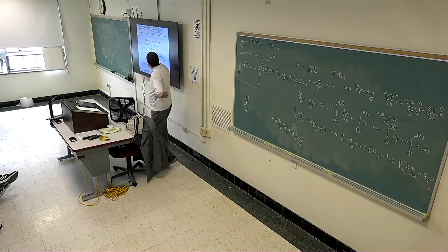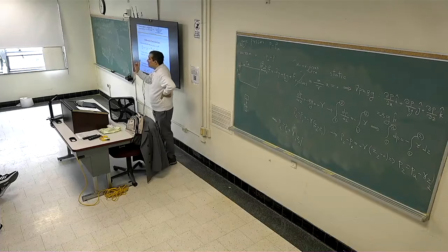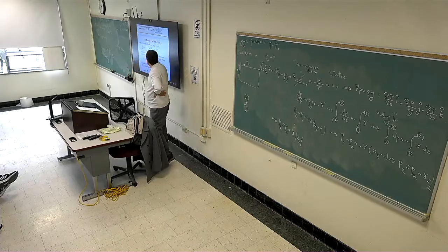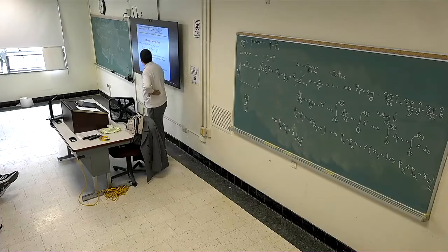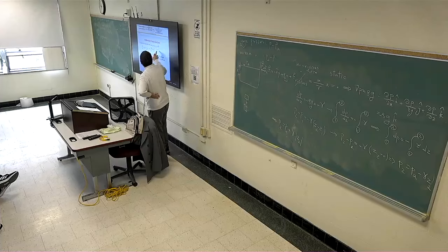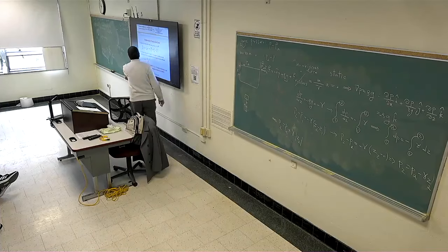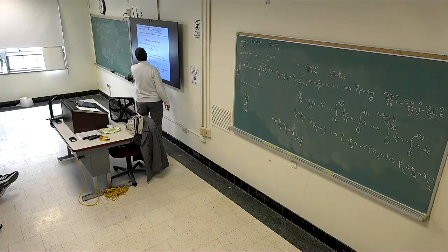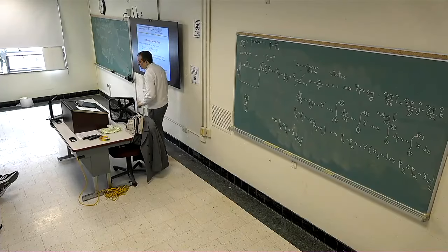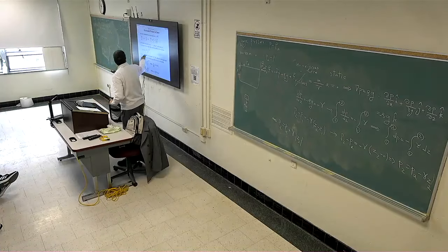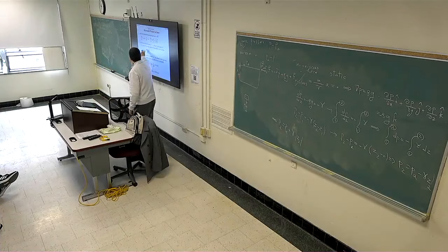For the right side, we can assume two conditions to integrate dz over T. The first condition: assume T is constant. So if I assume T is constant, T comes out of the integral. Integral of dz is z2 minus z1. So ln P2 over P1 is equal to minus g over R T0 times (z2 minus z1). So P2 is equal to P1 exponential of minus g (z2 minus z1) over R T0. You just need this equation.